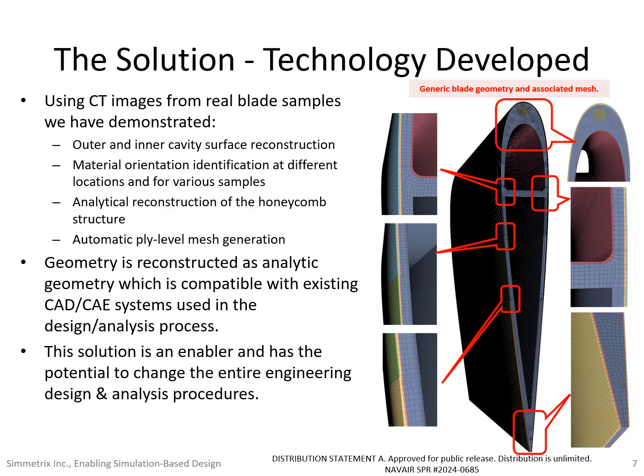Finite element analysis. Using blade samples that we had in our possession, we were able to demonstrate outer and inner cavity boundary reconstruction, identification of ply orientation, analytical reconstruction of the honeycomb structure, and ply-level mesh generation. We believe that development of image-to-finite element model representation technology has the potential to change the entire engineering design and analysis procedures, as well as asset management.